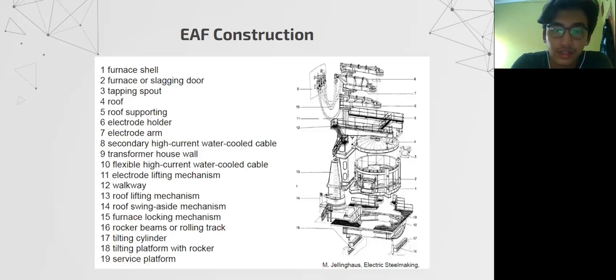This is electric arc furnace construction. Basically, the electric arc furnace is split into three sections. First, the shell, which consists of the sidewalls and lower steel bowl. Second is the hearth, which consists of the refractory that lines the lower bowl. And the third is the roof, which may be refractory lined or water cooled. The roof also supports the refractory delta in the center, through which one or more graphite electrodes enter.